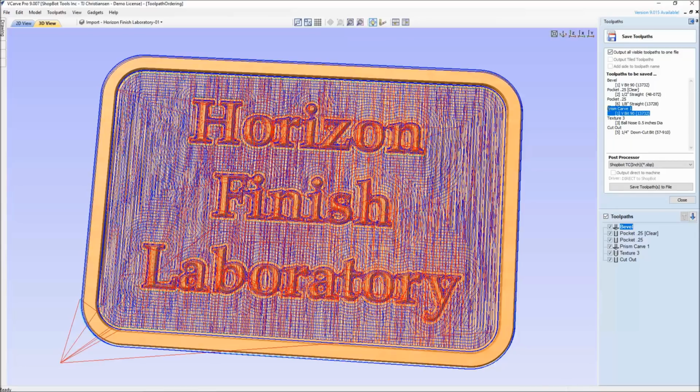In the case of if it was something where you had to carve something away ahead of time to pocket it to get to where that V bit would be, I could understand where you needed to switch out a bit and then put it back in later. But in this case, the way this file was drawn, the bevel was just put on first on these vectors so people would see what they look like in the preview as we were going through and drawing this. So right now this bevel does not need to be first.